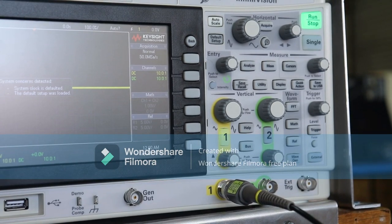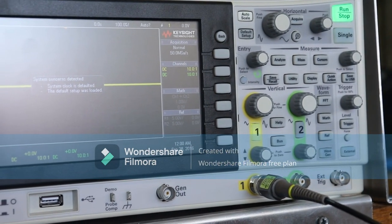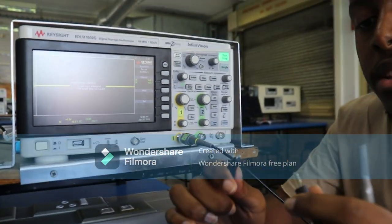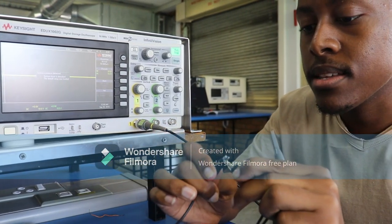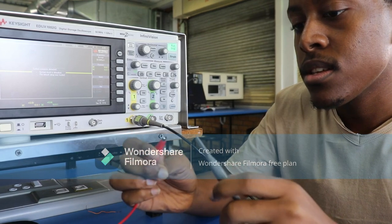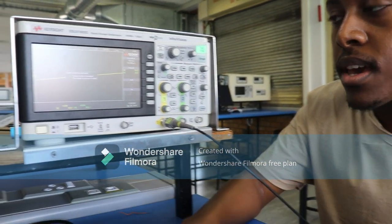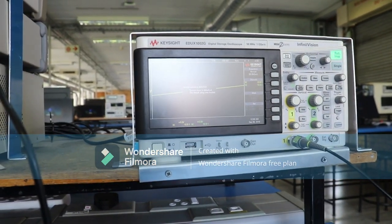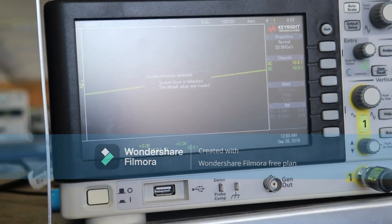Now, in order to use our oscilloscope, we actually need to use a signal coming from our function generator, which we set up earlier. You typically connect your black output to your negative terminal, and then your positive to your positive scope probe. Okay, now if you look on the screen right now, we can see a resemblance of a wave.